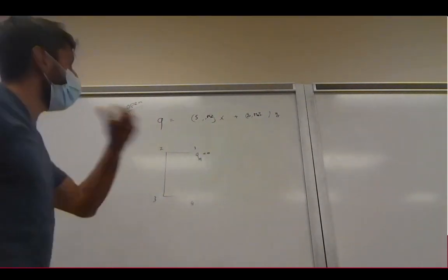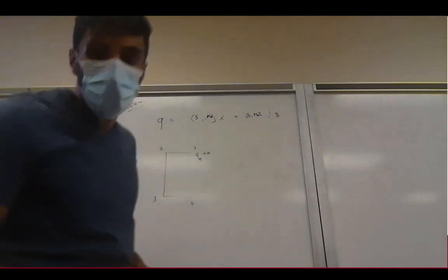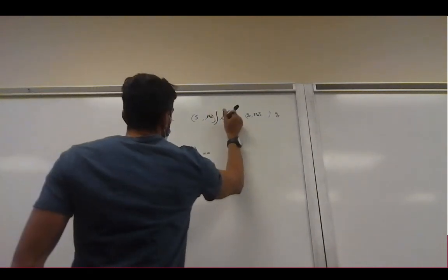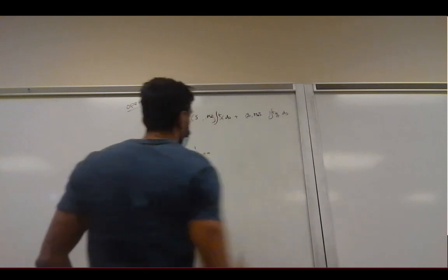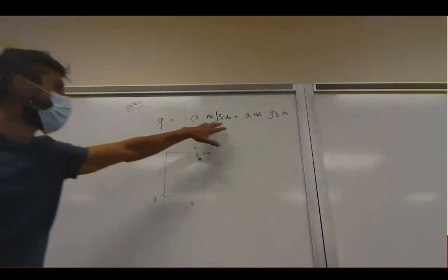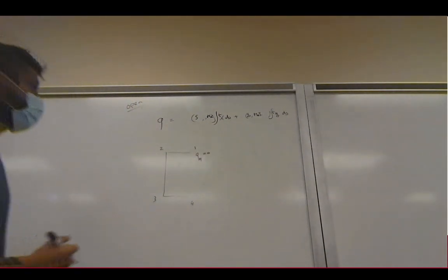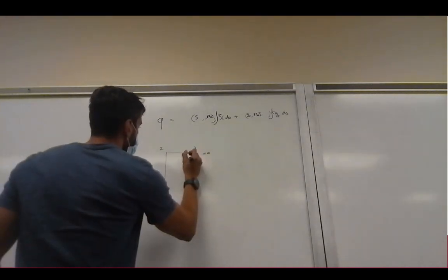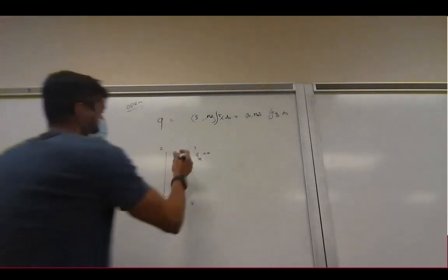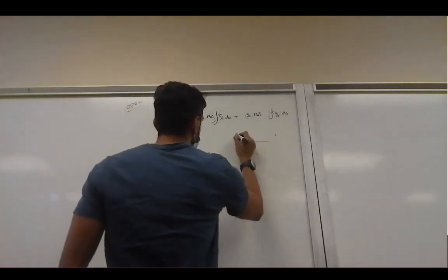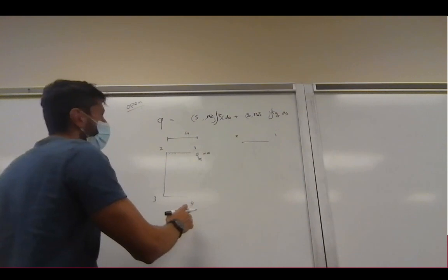So both shear forces x and y. So what are x and y in this case? We're talking about non-idealized sections, and there's actually an integral of t x ds and t y ds. And these two coordinates, x and y, are the positions along our cross section. But because now we're taking an integral, we need to know all the positions along the segment that we take the integral over.